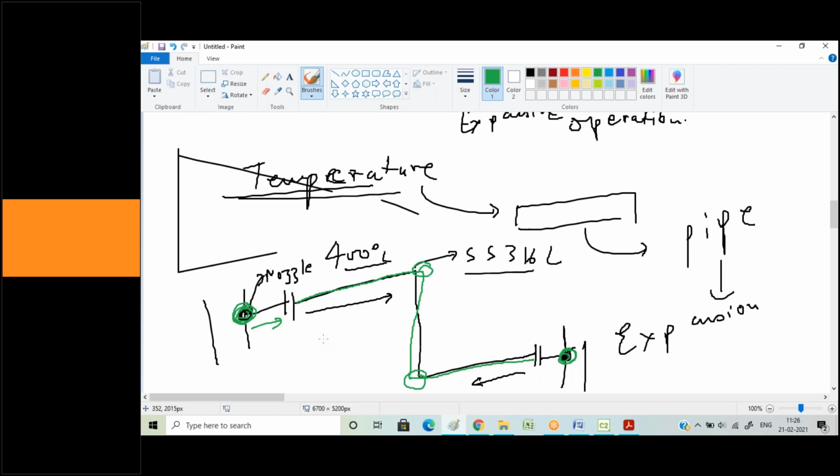A particular company that does any project keeps this as a criteria. What we basically do is keep it as 90 degrees. Any line whose operating temperature is above 90 degrees Celsius, we keep it for stress analysis. So this is one of the general criteria we do follow.